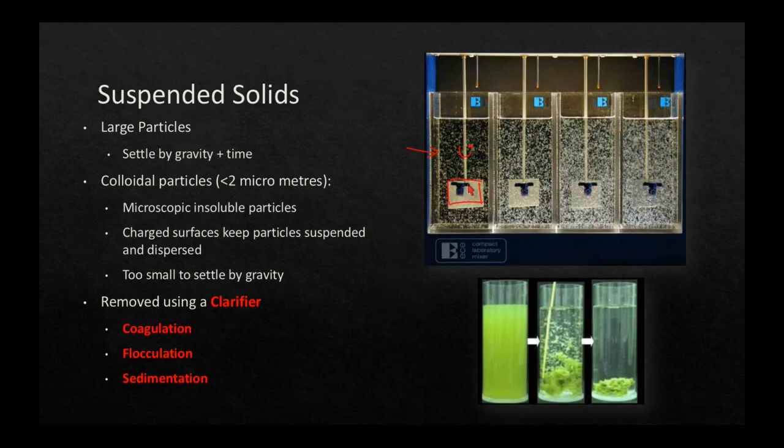It's going to mix the coagulant, and notice what happens over a short period of time, this is 1, 2, 3, 4, as time progresses, the coagulant has basically stripped away the charge, and now these little charged particles, these colloidal particles, are coming together.